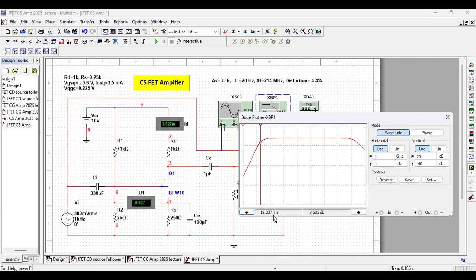The pre-amplifier stage decides the equalizing characteristics and distortion of an amplifier, where you use a FET amplifier, which gives a very accurate distortionless amplification, but the amplification ratio is small. And after this pre-amplifier, you may use transistor amplifiers so that the power is enhanced.